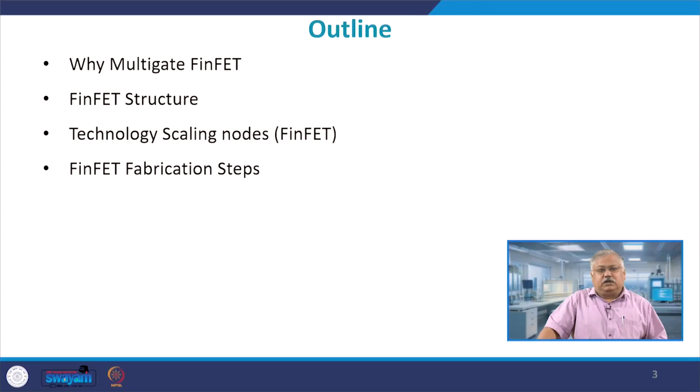What is the meaning of FinFET structure, technology, scaling nodes and FinFET fabrication steps. You already are aware of the fact that in our previous discussions so far, though I have not tacitly explained to you, but most of you are aware that as you move in technology node from a higher channel length to much smaller channel lengths, you end up having these second order short channel effects, right? And the rule of thumb is that the more you are able to surround the channel, the more the gate has control over the channel, the lower will be your second order effects.